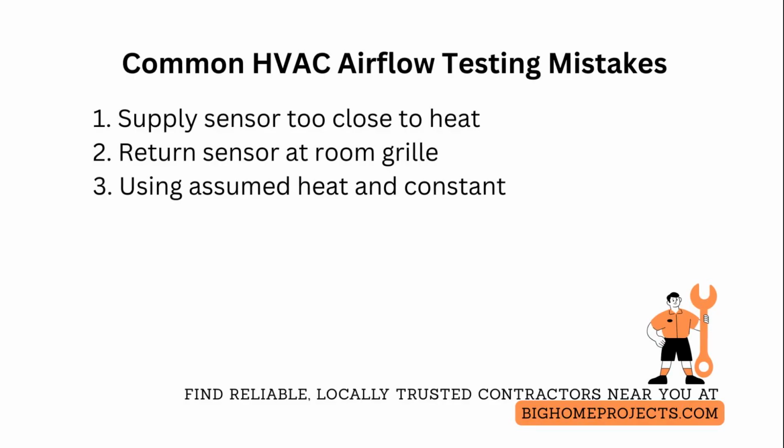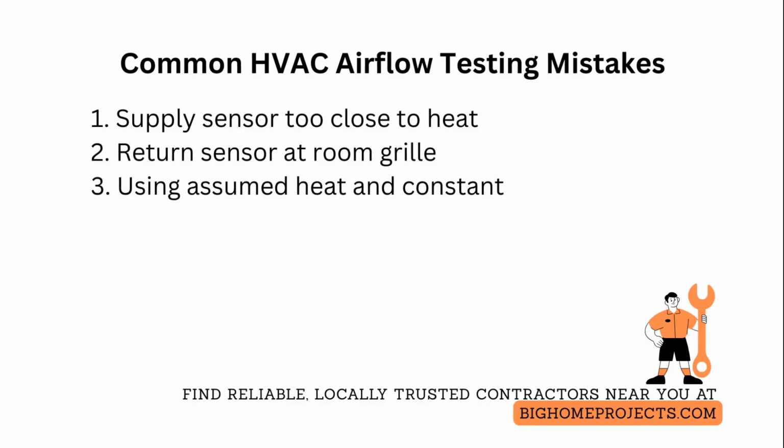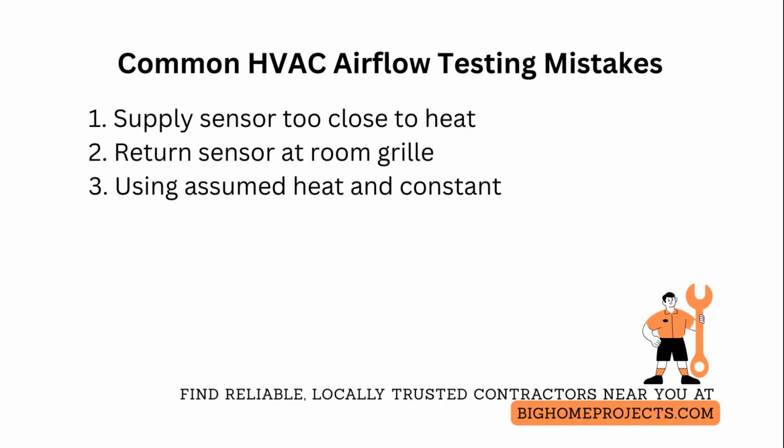One of the top airflow measurement errors is installing the return temperature sensor in a room return grille instead of the return plenum, which adds room heat gain and underestimates true temperature rise. Correct this by mounting the sensor in the return duct within 12 inches of the air handler inlet, upstream of any filter bypass leakage, and confirm no outside air is mixing between sensors.